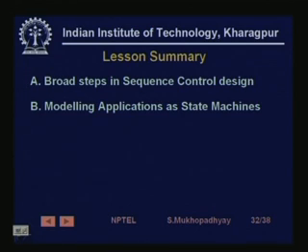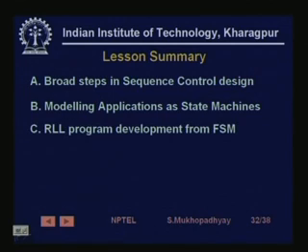We took a very simple industrial application like a stamping process and built its state machine, and then we have shown how, given the state machine, very mechanically you can arrive at how to structure your program and then write the transition logic, the state logic and the output logic. And we have seen that this is very much expected to lead to error-free programs.